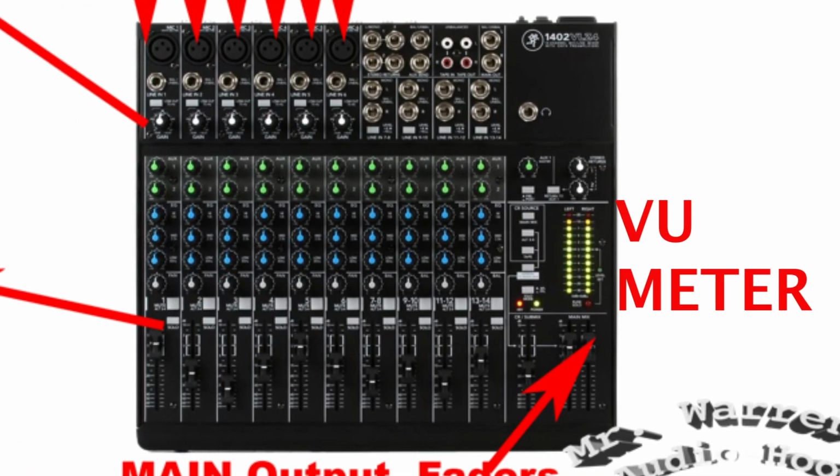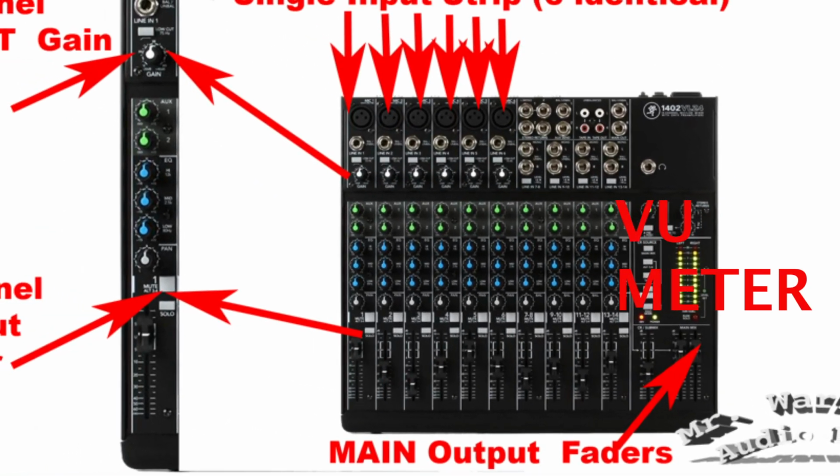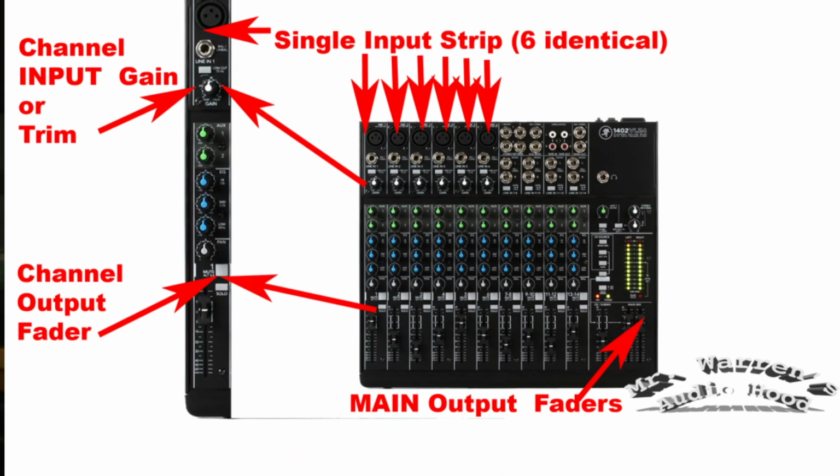To set this up correctly within the mixer, we need to take the mixer's main output fader and set it to its nominal position. If the mixer has a VU meter of some type, this is a helpful tool. Next, we open the channel output fader to its nominal position, as indicated by the picture. We then plug a microphone or CD player, whatever our source is, to the input of the mixer, and slowly open the trim pot until the VU meter hovers roughly between minus 10 and 0.